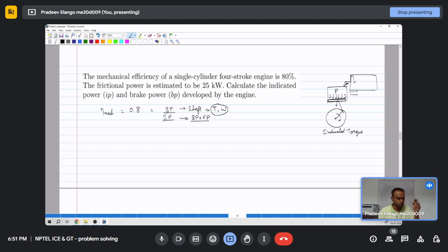This paper keeps rotating. Crank angle is this angle, theta. There is a gear system between the crank and the paper, so the paper sits on a cylinder and rotates, and the indication system has a spring that ensures the displacement is proportional to the pressure inside. With this we can estimate the power output of the engine, and that is indicated power.